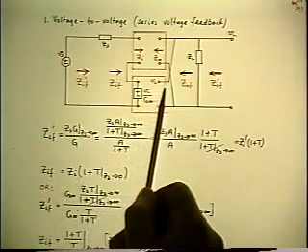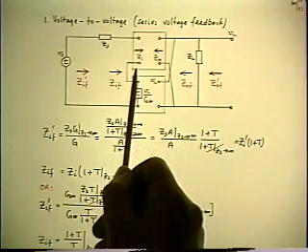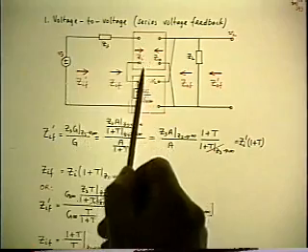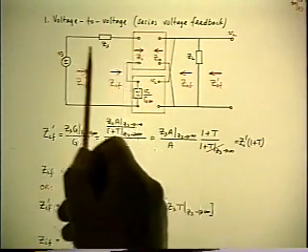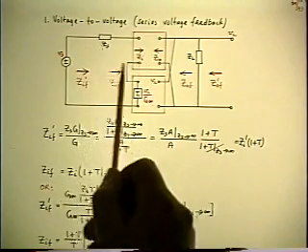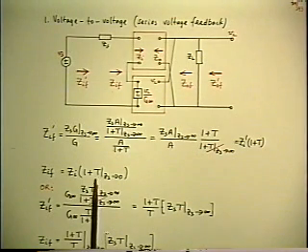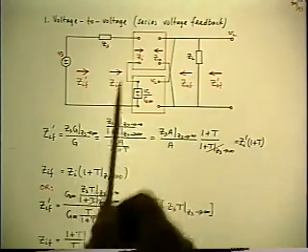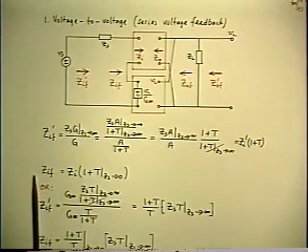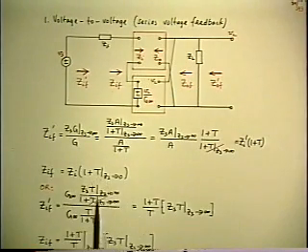The argument is that there's a signal coming out of the feedback path, and what gets into the front end of the amplifier is determined by the impedance divider formed by Zs and Zi, which is a loss factor. Therefore, if Zs goes to 0, that loss factor rises to 1. So whatever value it started from, it gets bigger. So T with Zs 0 is bigger than the original T. So the inside input impedance with feedback is equal to its open loop value raised by a larger factor than F.